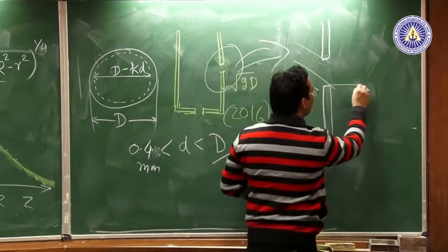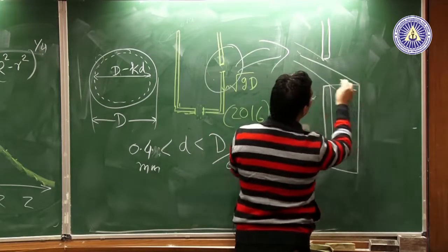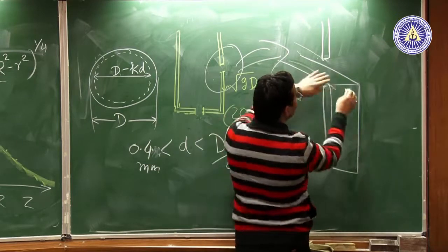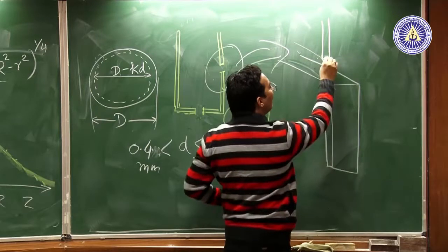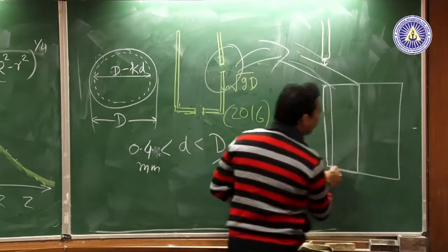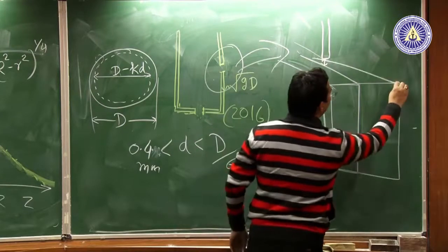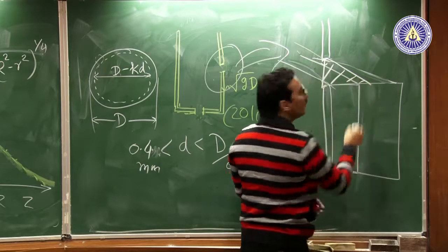The moment I increase my thickness, the material encounters a region which makes it form a heap, and only some relatively smaller area is available. If I make the container thickness big enough, this will completely block the flow, and you will see no flow at all.